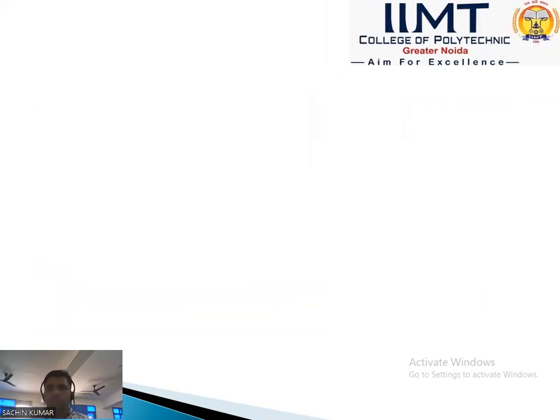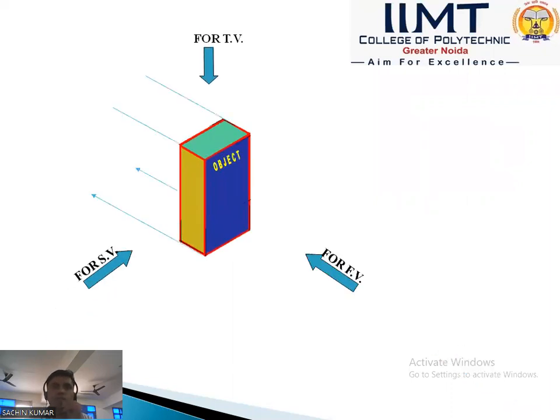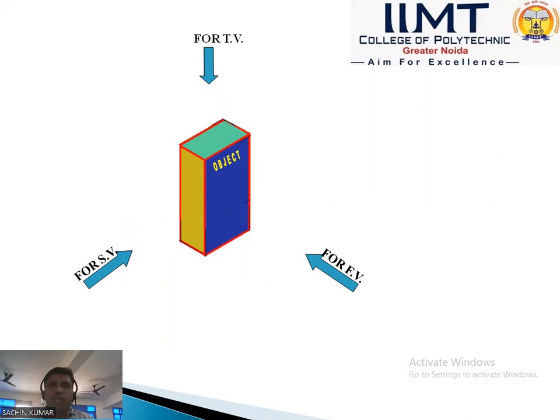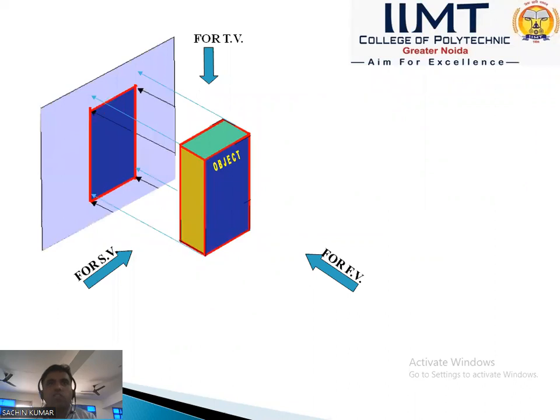Now we will discuss the projectors. Here is the object, with the front view, top view, and side view. These lines are the projectors, as we discussed in the previous slide. The first condition of orthographic projection is that these lines are parallel to each other. The second condition is that the plane of projection is perpendicular to the projectors. So in orthographic projection, two conditions are satisfied: the projector lines are parallel to each other, and the projectors are perpendicular to the plane of projection. That is called orthographic projection.